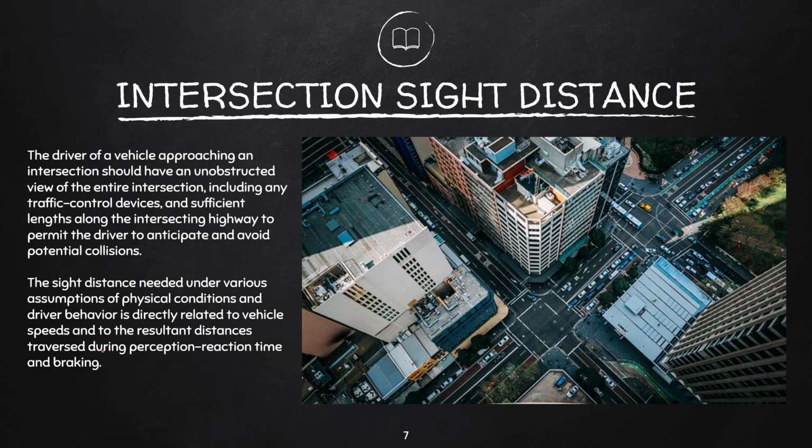The general rule is that if the driver or the vehicle is moving at a higher speed, of course there is more distance that should be provided, more sight distance that should be provided. That is why one way to prevent accidents, if the provision of this relatively long sight distance is not applicable, is that we limit the distance or the speed in these road sections.